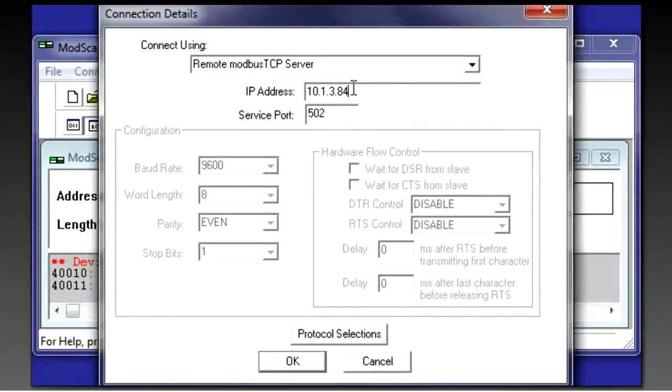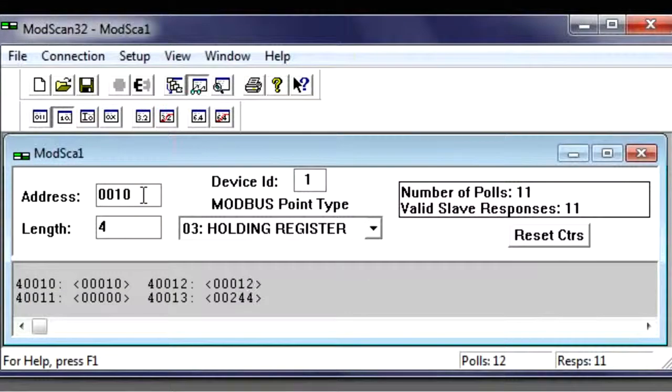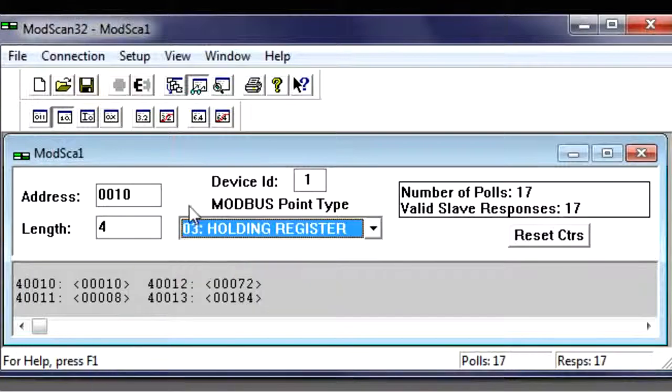I'm going to go ahead and do a connection. I'm going to connect to this remote Modbus device. You just saw in the previous settings that I have an IP address assigned for this. That's all you need to do from your Ethernet side: say go to the Modbus device, here's the IP address of the device I want to go to, and then connect. When I connect, I'm going to define the devices I want to look at. Within this specific PLC, a little Modicon Momentum, now available through Schneider Electric, the Modbus registers I'm looking at are going to be holding registers.